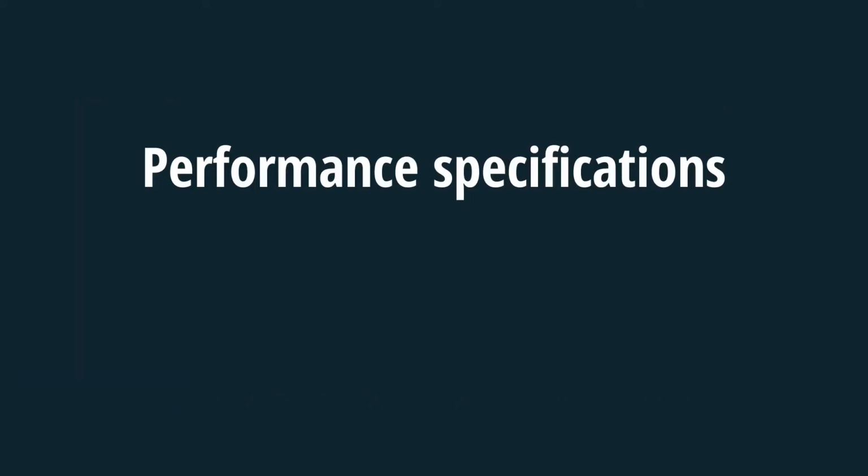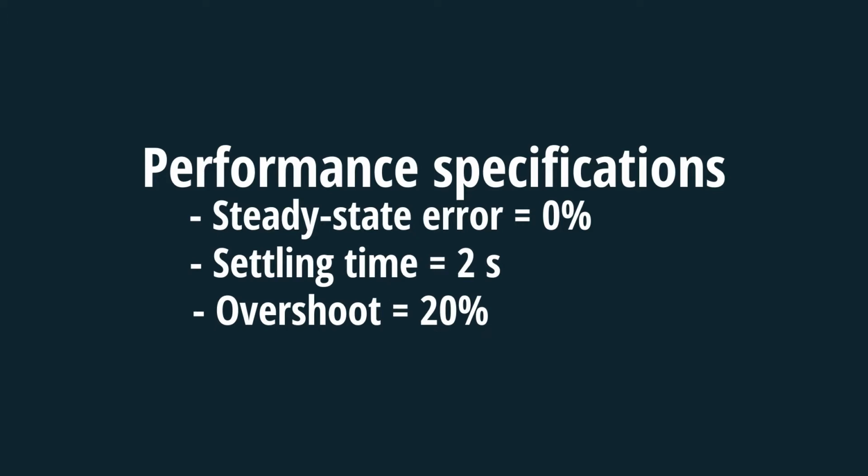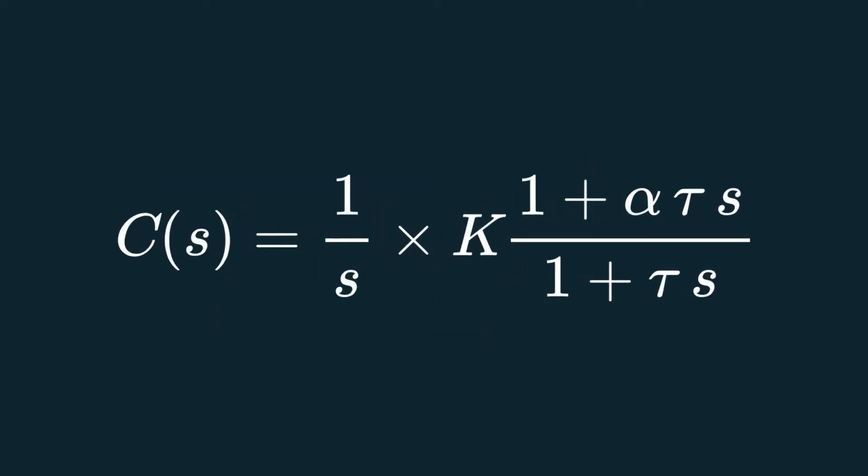Specifications are kept the same: no steady-state error, a settling time of 2 seconds, and an overshoot that does not exceed 20%. So the chosen structure is an integrator followed by a lead compensator.